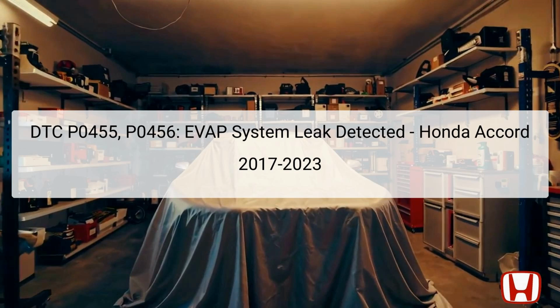The EVAP system captures gasoline vapors from the fuel tank and routes them to the engine for combustion, thereby reducing harmful emissions. Components such as the EVAP canister, purge valve, and vent shut valve play critical roles in this process. Precise diagnosis is crucial, as any leaks can lead to increased emissions and affect performance. Understanding how to identify and fix these issues will enhance the reliability and sustainability of your Honda Accord.